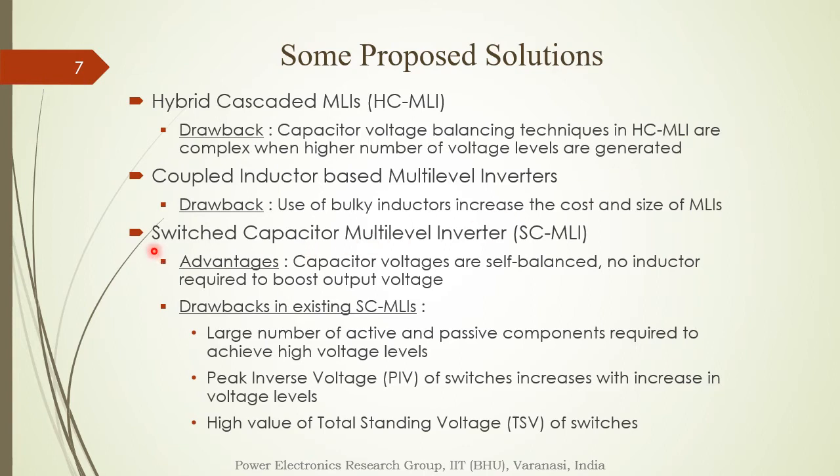Then, due to advanced research, switched capacitor based MLIs were developed, where the capacitors are self balanced. No inductors are required to boost the output voltage, and no external circuit, additional voltage sensing circuits or signal conditioning circuits are required to balance the capacitors in these switched capacitor based MLIs. The main drawback is that a large number of active and passive components are required, and the peak inverse voltage of the switches increases with the increase in voltage levels. As the PIV increases, the cost of the switches also increases.